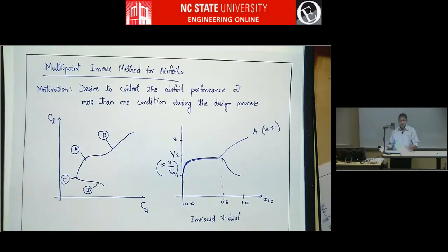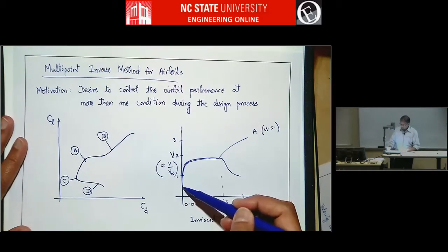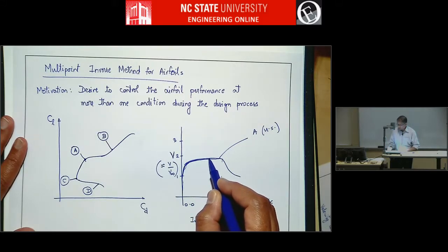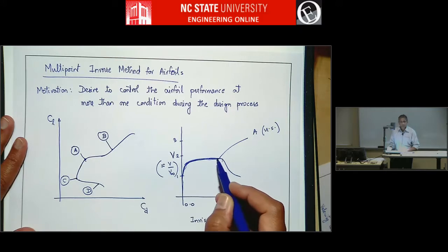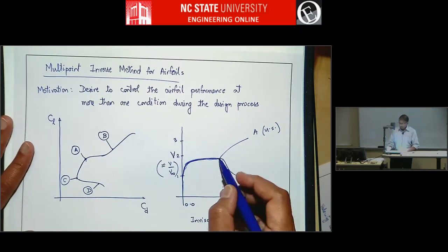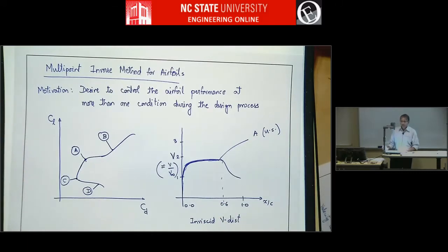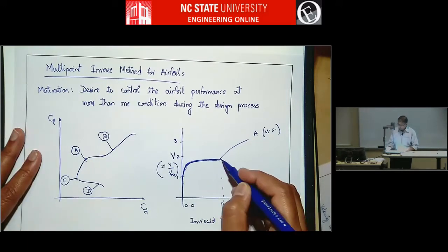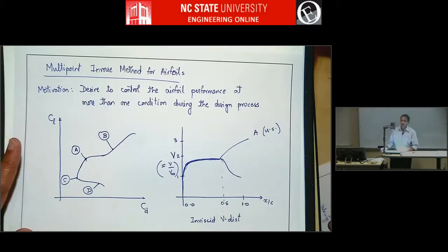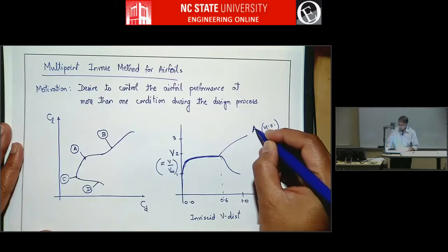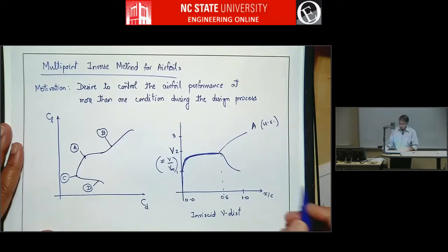So if, let's say, there's a Reynolds number of 3 million, then at 3 million, this is almost zero pressure gradient, but it's slightly favorable. That means this airfoil, if it's a clean, smooth airfoil, will have laminar flow all the way to about 60% at this lift coefficient. So this is at condition A, lift coefficient A on the upper surface.